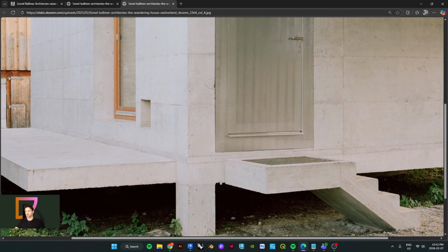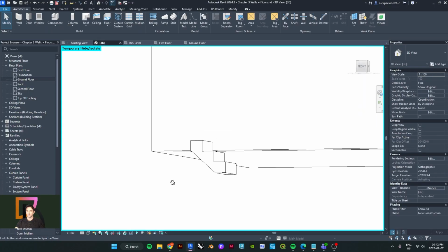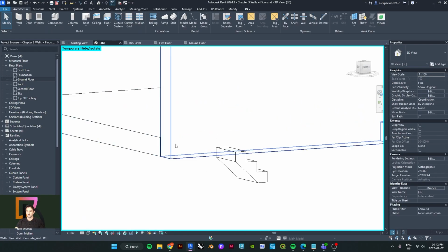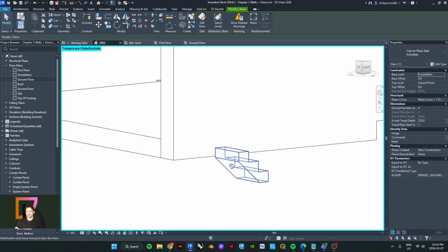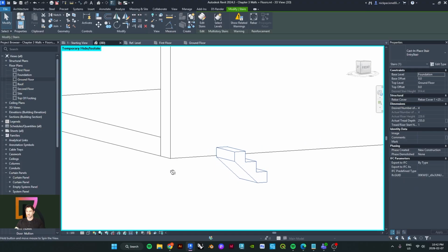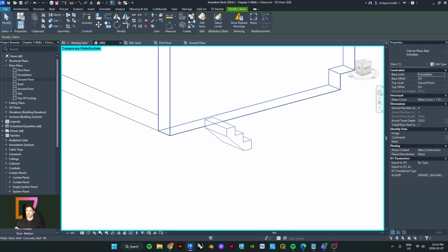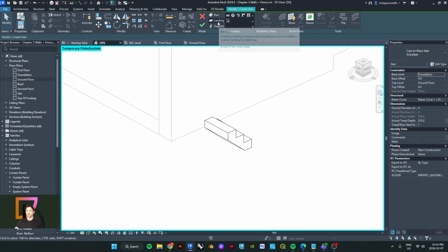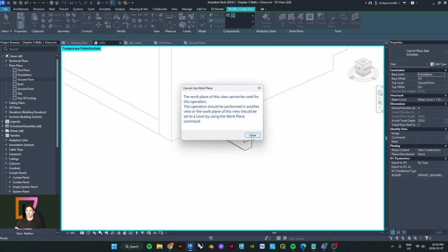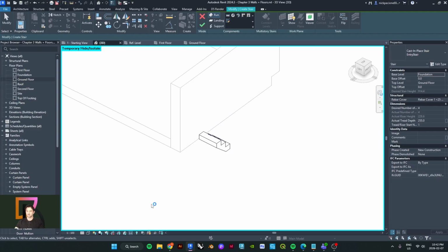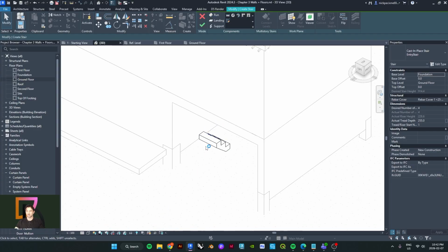So what we are going to do is come into the stairs here. I'm going to go edit stairs, and then we're going to take a landing, and we're going to sketch it out. So you can do this in 3D. Typically, it's not letting me because I think we're in isolation view, so I'm going to come back to that.